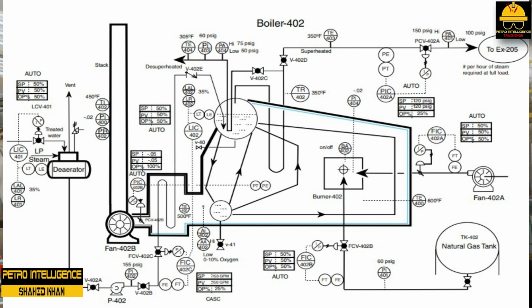As the temperature of the water inside the generating and riser tubes increases, the density of the water decreases and initial circulation is established. Bubbles begin to form and rise in the water, increasing circulation and pressure. Each time the water passes through the tubes, it picks up more heat energy. When the pressure increases to slightly above the system pressure set point, steam will flow to the header. Inside the upper steam generating drum of B402, steam and water come into physical contact, saturating the steam. This saturated condition means that for every temperature of water, a corresponding pressure of steam exists.